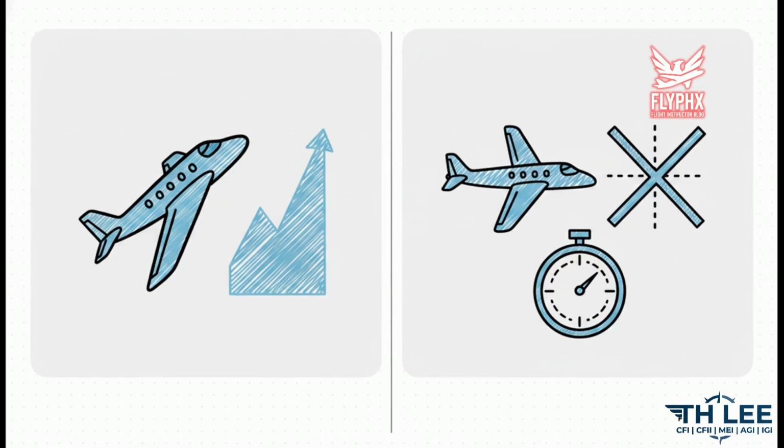Instead, you have to whip out the E6B. Use the inner scale with your non-standard temperature to find true airspeed and the outer scale to get your indicated airspeed. The big takeaway here? Always read the fine print on your charts.